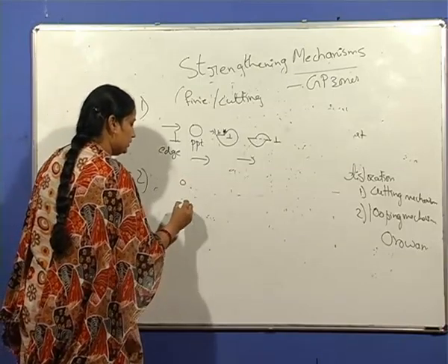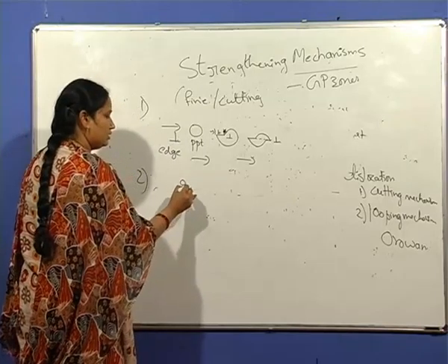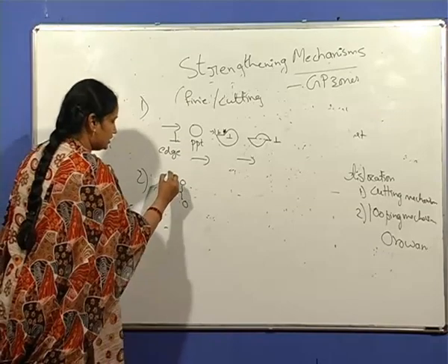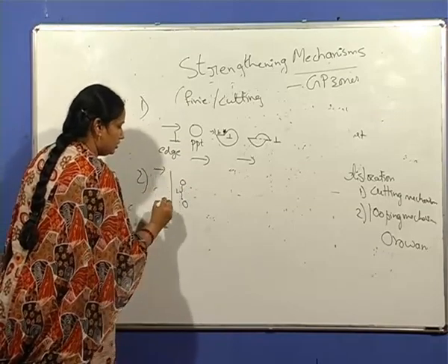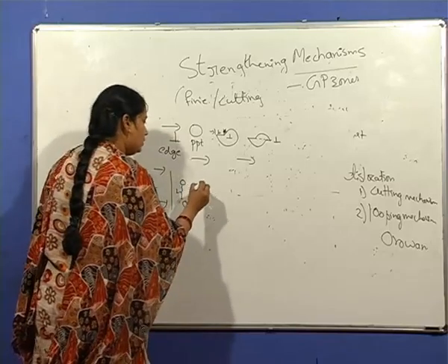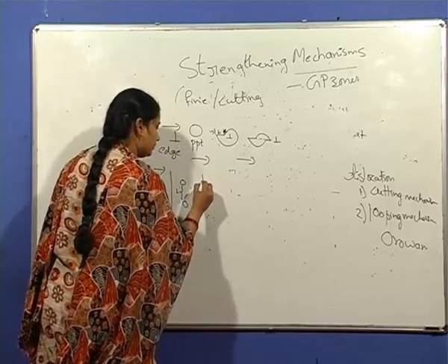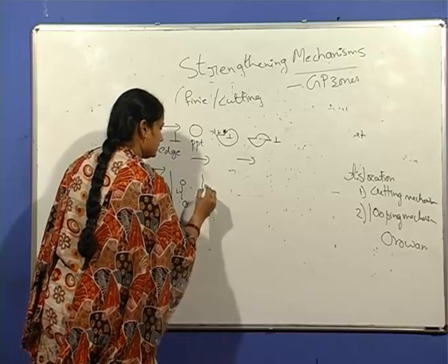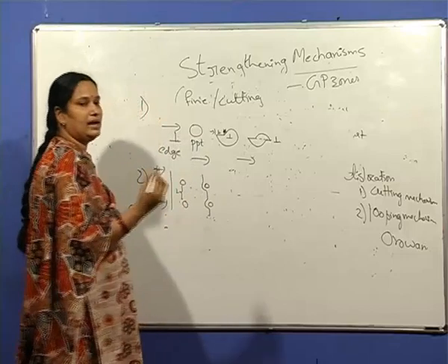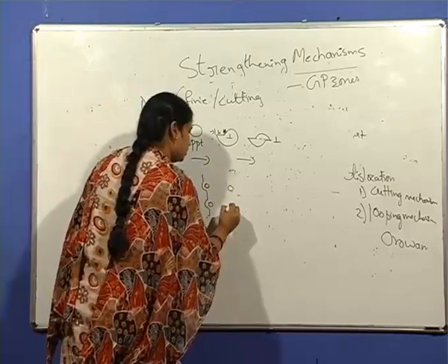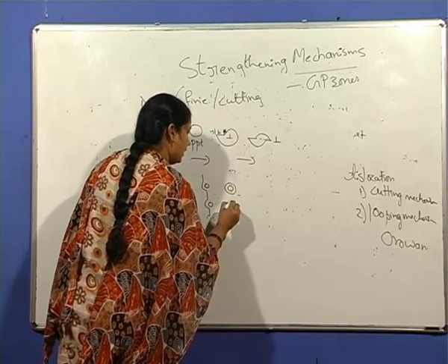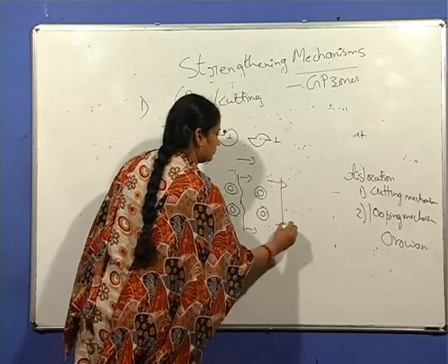These are two precipitates separated by the distance L. For a dislocation to overcome this obstacle, it has to bend around the precipitates and then bypass. Bending around requires large amounts of stress.